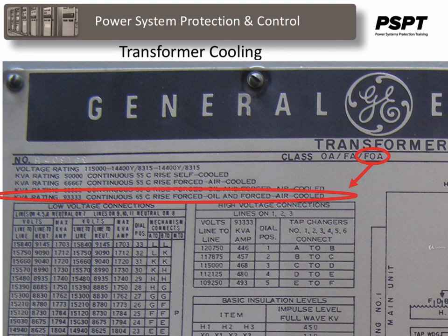The mechanically assisted equipment is usually automatically switched on as the operating temperature rises, but it could be operator initiated. In either case, close observation is required, as this expensive equipment is operated close to the rating limits. In any event, protective relaying should take it out if limits are exceeded for too long.